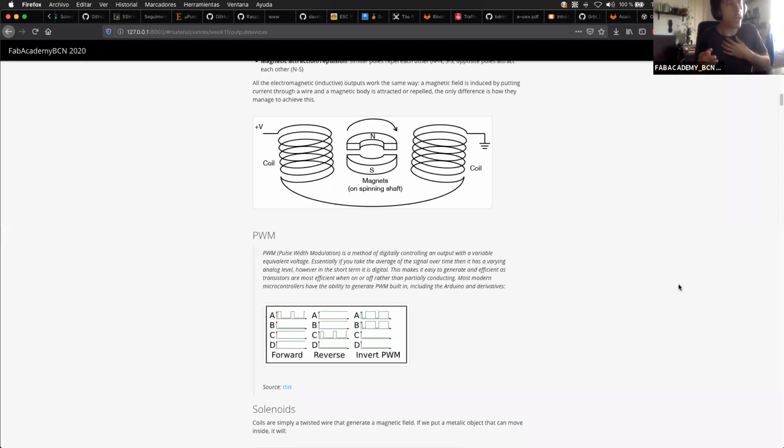In that way, by increasing the size of the motor, you can increase the torque. That's why very small motors have very little torque, and you can even stop them with your hand or with your fingers, while much bigger motors can give you more torque because they can hold more current without burning.